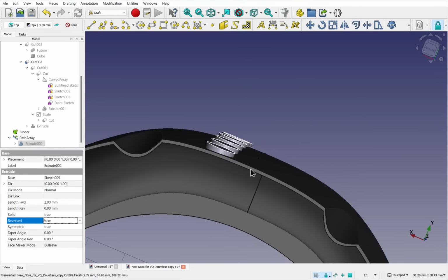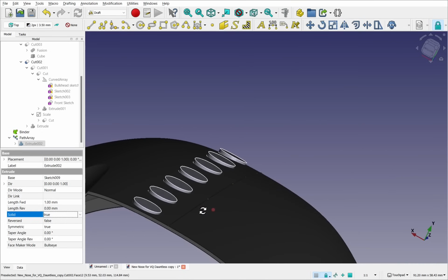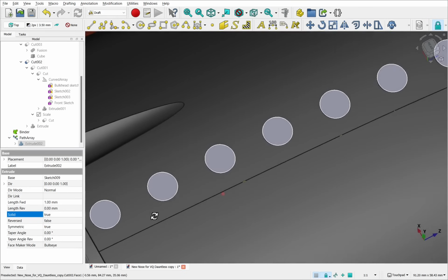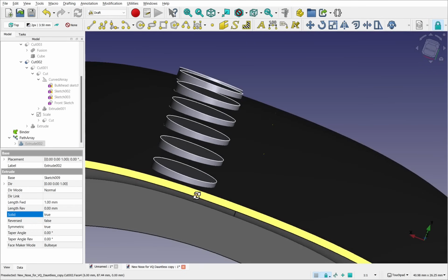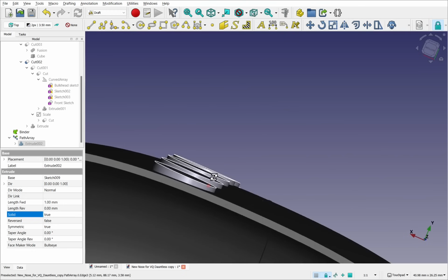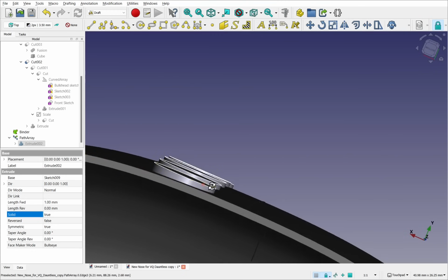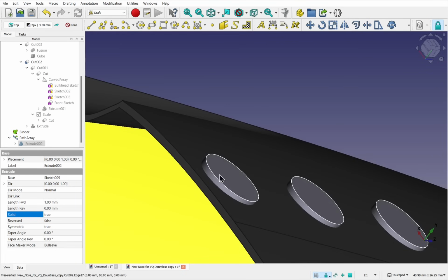So there needs to be a bit more tweaking of the variables to allow this to align properly. There's a 1mm extrusion there, but you can see it's not totally right. There is still some problems because we've used the translation. It's not tangent correctly to this surface because we've got curvature this way as well as curvature this way.